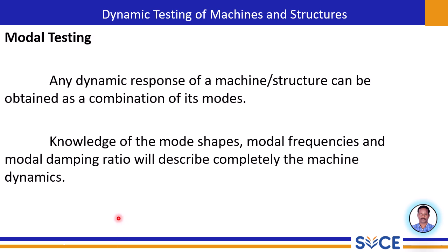Next, important thing is the modal testing. Any dynamic response of a machine or structure can be understood as a combination of its individual modes of vibration. Think of these modes as the fundamental building blocks of how a structure will vibrate, just like a musical chord is a combination of individual notes. The complex vibration pattern of a structure under any dynamic load is essentially a superposition of its various mode shapes.